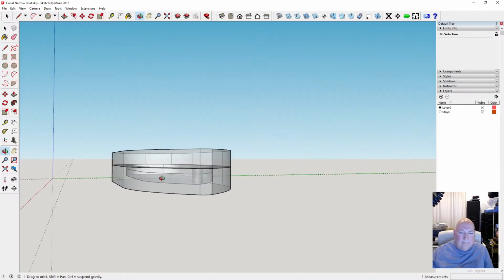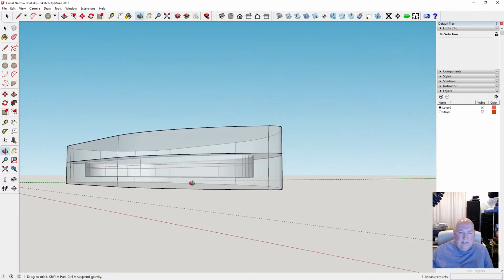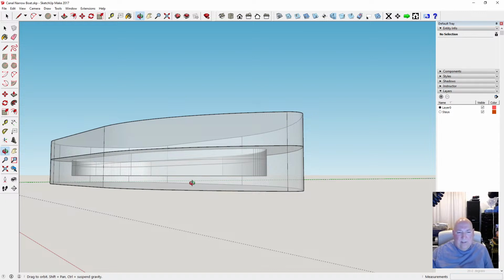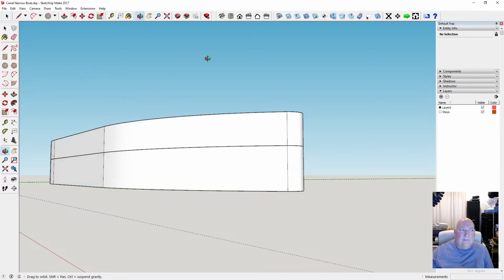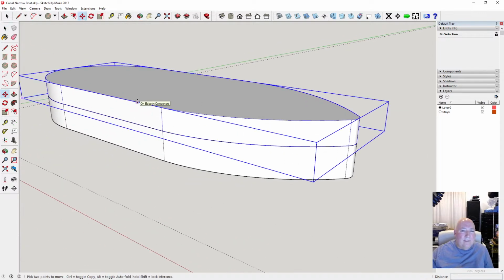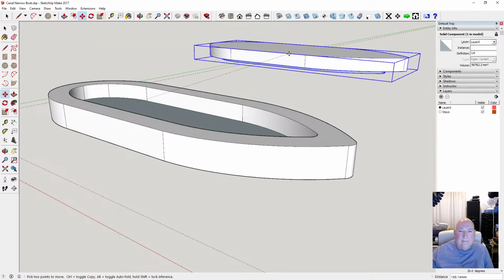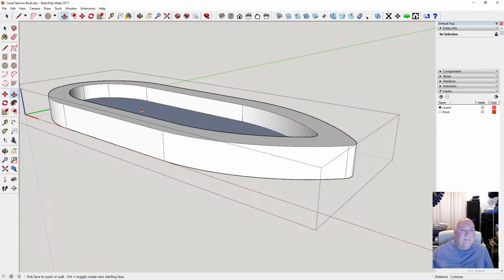So how can we expand on that? We need a certain thickness of material here, otherwise it'll be too thin. Do we need 4mm though? Probably not. We could get away with a bit less than 4mm, so let's do that. Let's just move that out the way for a bit. Let's drop it down 2mm.